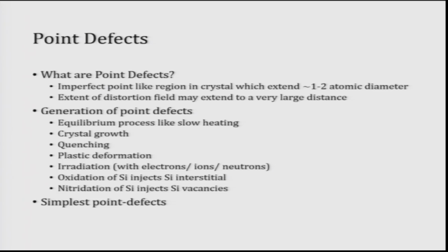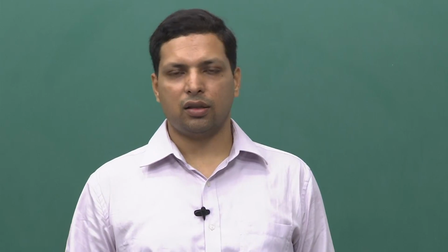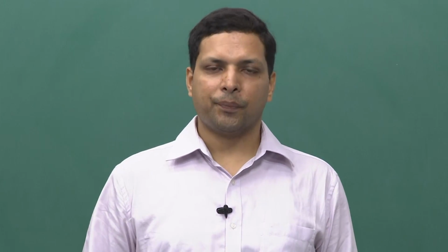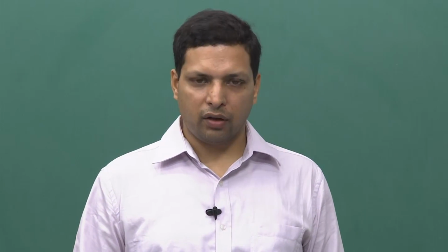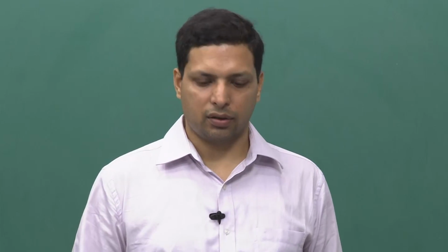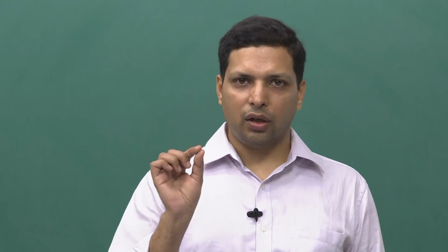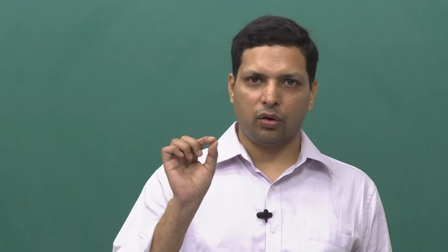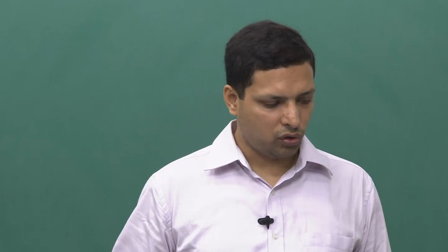Let us say we are in a single pure material, and to be even simpler we will talk about metals. Then we are talking about vacancies. Even vacancies can be mono vacancies, di vacancies, or cluster vacancies, but to begin with, we will just start with mono vacancies. So, we are talking about unit point defects or unit missing atoms, which are mono vacancies.